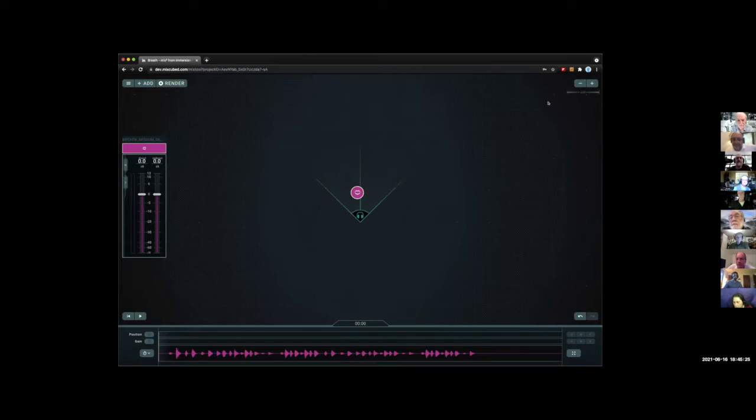Up here in the right-hand corner, you will see the grid that you're on. It tells you the distances of each one of those blocks. As I zoom in, these blocks represent a meter. Now as I zoom in further, these represent 50 centimeters. As we move back out, you can also right-click and it will reset the frame to wherever your distance is. That's kind of natural. So if I move this really far away, I can reframe this by right-clicking or double-clicking, and it will automatically recenter everything with a reset view.